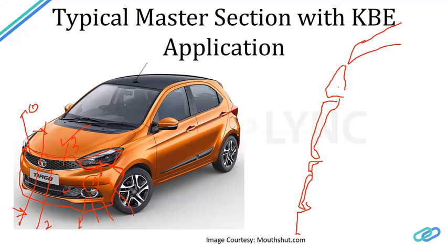What happens is when I start creating the template, first I will create this part. This is not related to my part, but I'll be taking the input from this part. So this part will have an input of the first flange. This is called a first flange from this part, from the bonnet. So I'll take this input. I will create the parting line and the first flange of my part, which is the top bezel. This is the part I'm talking about. So this will have the first flange, and again this is also a first flange.